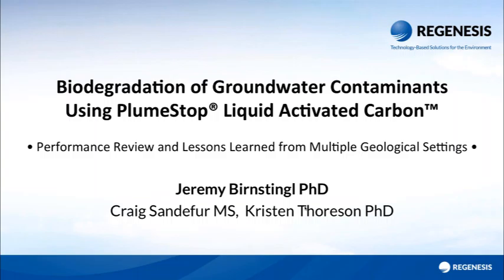But because of the extra sorptive capacity of the PlumeStop, the effective FOC, the actual sorptive capacity we get of that tiny change, is going to be something like 500 times greater. It's going to depend on the contaminant and the concentration and the isotherms and all of that, but we might actually change the FOC by 0.1%, but we might get an effective change in the FOC in terms of retardation of 1,000-fold for that. So we're not going to block up or clog.